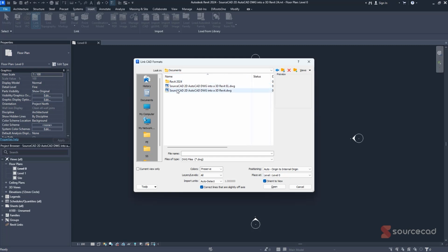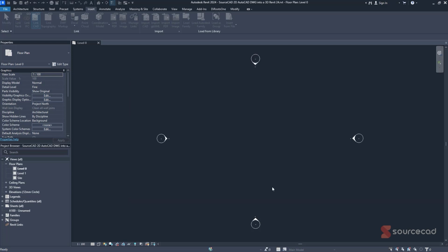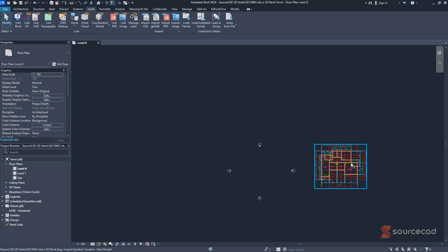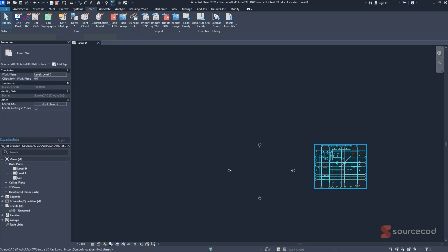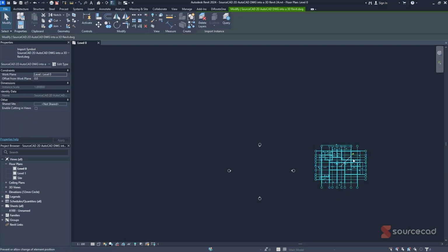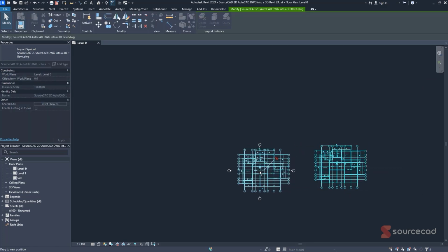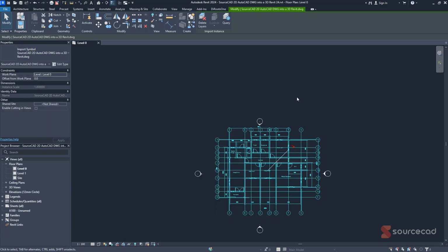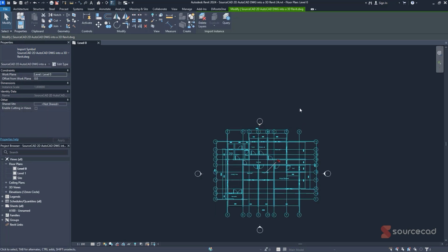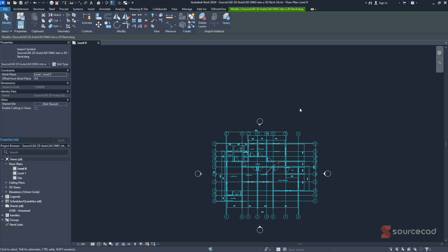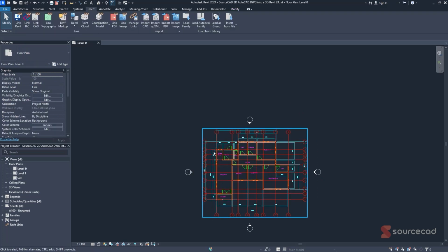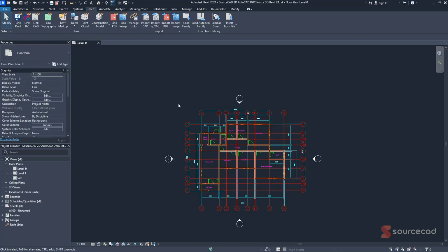Let's see. We're going to simply go to our floor plan using the same command that we were using last time. Click on open, and just like that, it has brought this drawing into our Revit software. So the answer is correct. You can link your CAD documents into various Revit documents, thus making designing as a team easier, especially when you're sharing a working folder. So this is how our DWG looks.